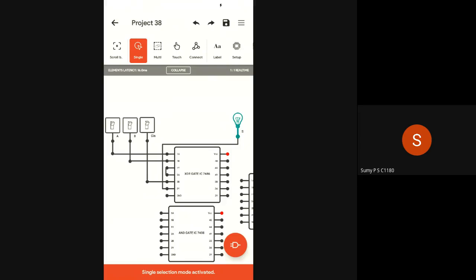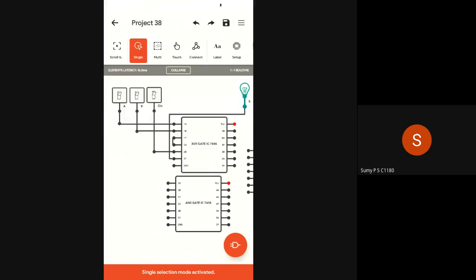Correct. Okay. So what I am going to do is use the AND gate. Already I am having A, given in 1A. I am having B, given in 1B. AB is obtained. What other AND term do I need? C in. Actually it is not C, it is C in, and A XOR B, which is already available. Where is A XOR B available? It is available in 1Y. Correct? A XOR B is already available in 1Y. So from there, I am going to take it to 2A.